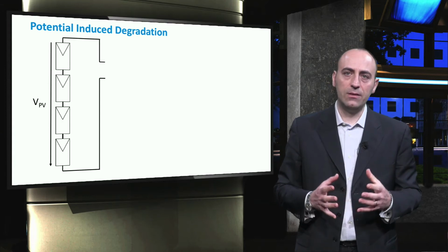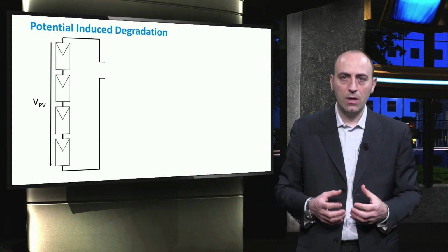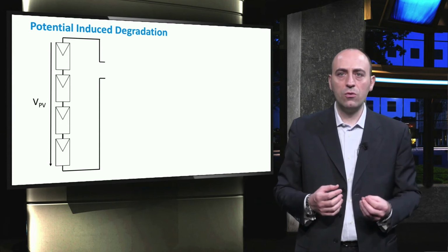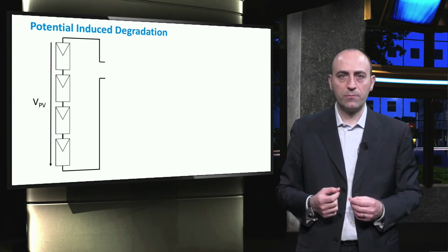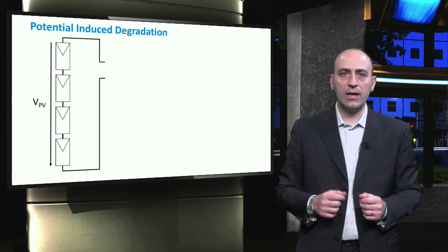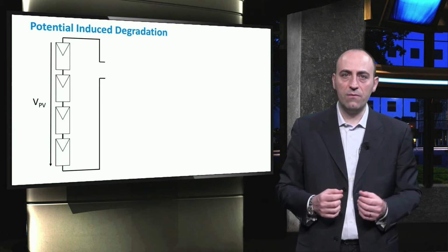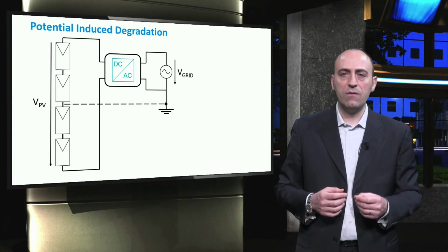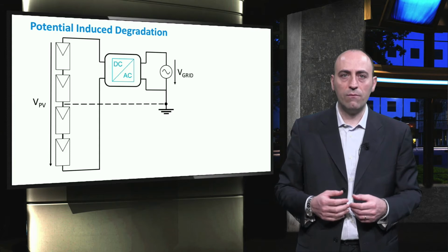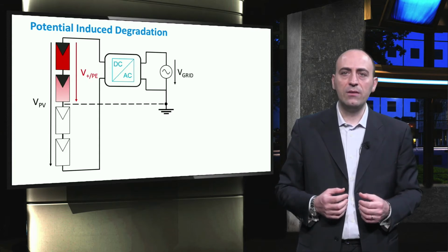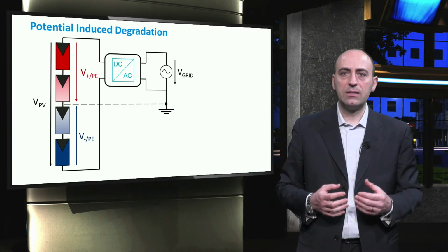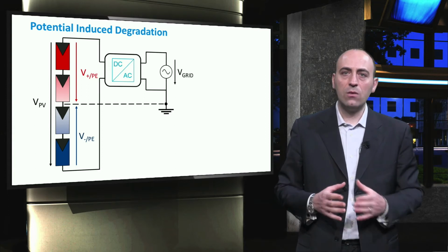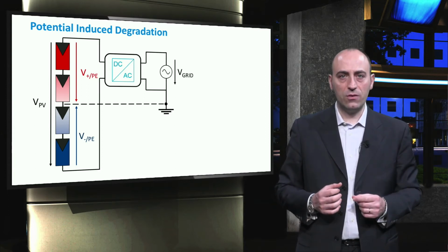The PV system and the environment interact to cause PID. This is mainly due to the fact that humidity and dust on the panels can cause sodium ions to affect the module's performance. Let's take a PV system connected to the grid via an inverter into account. The neutral point is in the middle of the system, so a positive pole shows a positive potential or a voltage against the ground. In a similar way, there is a negative pole. Typically, the last cells have a potential of minus 200 to minus 350 volts, depending on the length of the string and the type of inverter used.